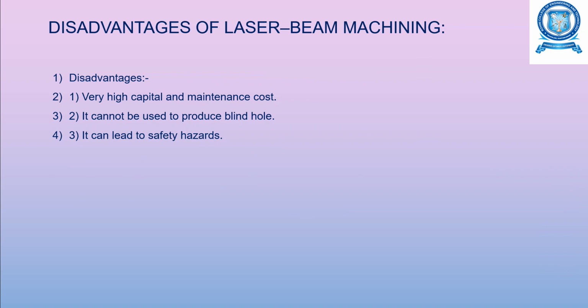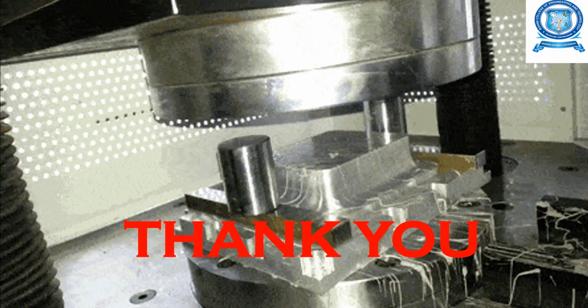Disadvantages of laser beam machining are very high capital and maintenance costs. It cannot be used to produce a blind hole, and it leads to safety hazards.